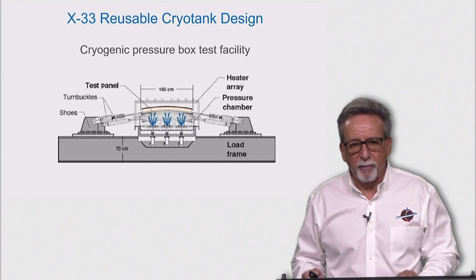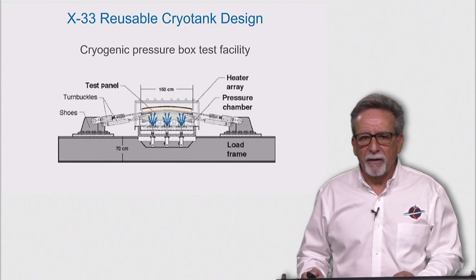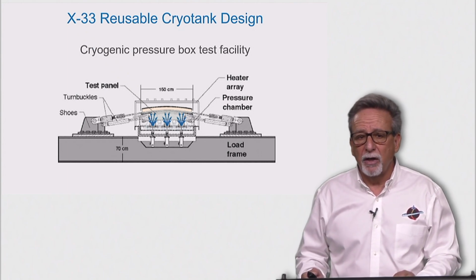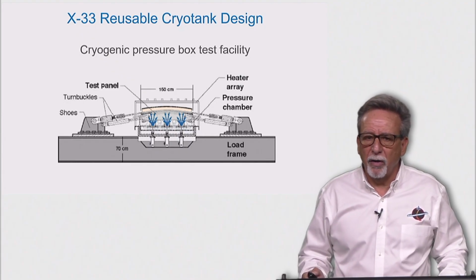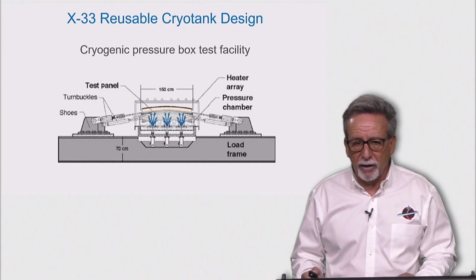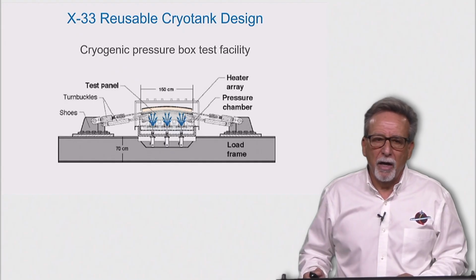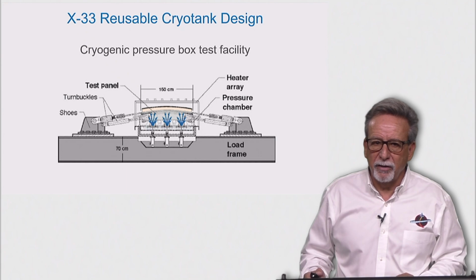Finite element analysis performed at Langley predicts that the strain distributions developed during testing in the CPB will be similar to strains seen in full-size cylindrical tank designs, in a 0.75 meter by 1 meter region in the center of the test specimen. The cycling with mechanical pressure and thermal loads on full-scale assemblies of tank walls with cryogenic insulation, thermal protection system, and integrated vehicle health monitoring can all be tested during the testing of a full-scale subcomponent.